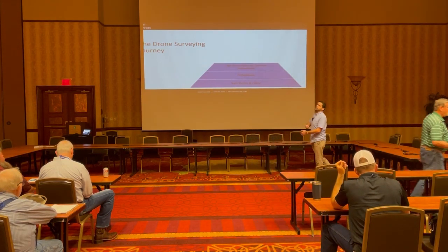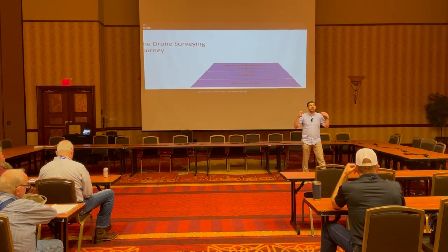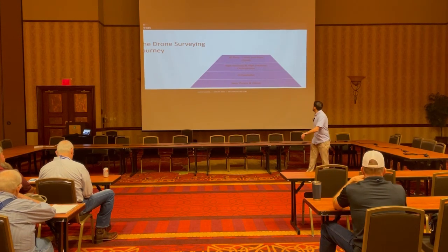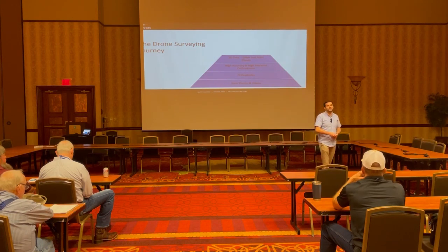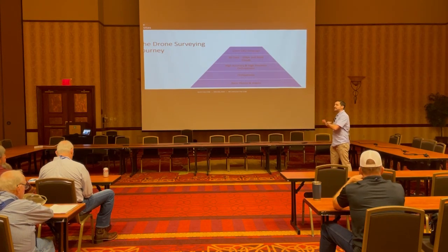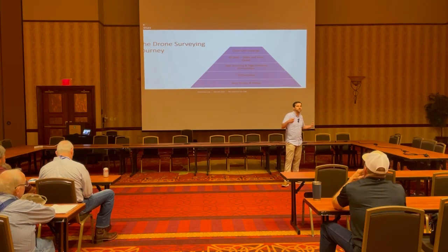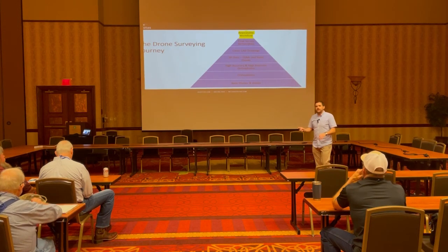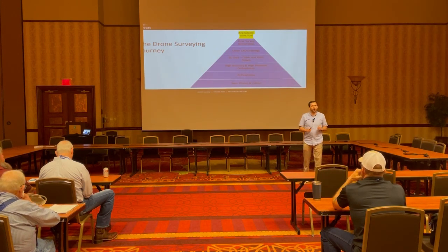Then you start adding in your control points, maybe RTK data. You start geo-referencing it to really get higher accuracy when you're actually mapping this, extracting your data. Then you start working in 3D, DSMs, point clouds, extracting topo data. And then you kind of start getting it into CAD as well, clean CAD drawings, merging it in with all of your other data, with boundaries, with prior surveys, that sort of thing. And then finally getting it to your final survey deliverable, but at the absolute top is actually turning this into a repeatable workflow. And that's often the hardest part for most people.